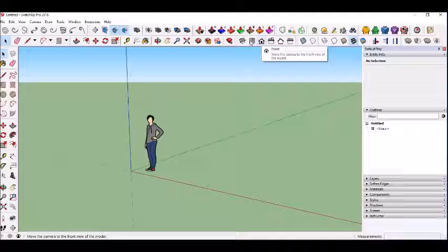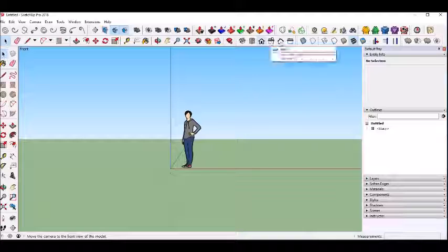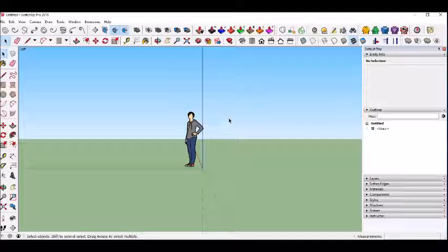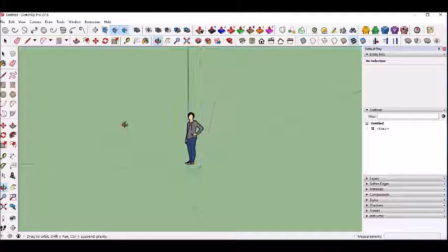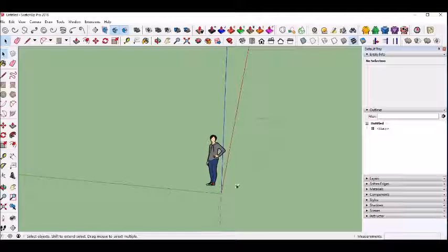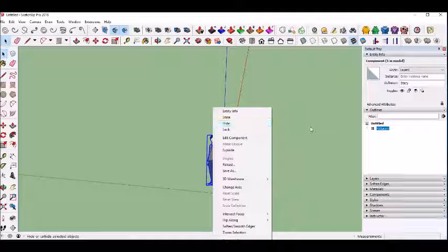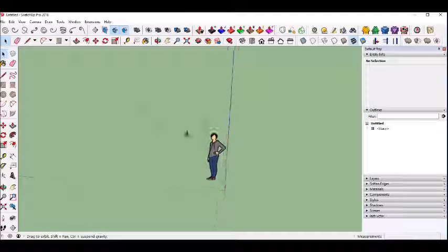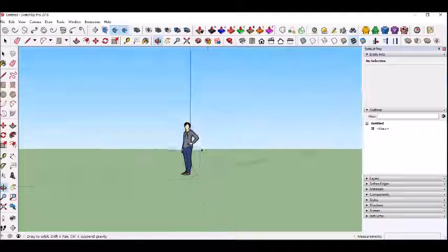These are your standard views. So ISO. If you have a three button mouse, the middle mouse button, if you click it and hold it, is rotation. Now to pan, if you hold left shift, middle mouse button again, it does this. Left click is select, right click is options if you right click on an object. So that is actually really basic.